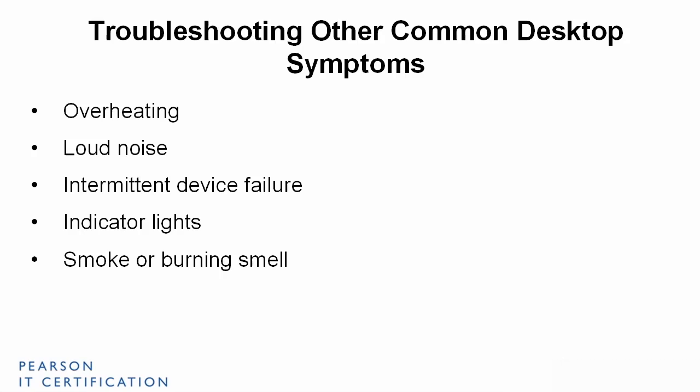Some power supplies have a burn-in period of about 24 to 48 hours where there is a slight odor. That's a little bit different, and that may be normal. Now, if you have a system you're working on, you'll probably just want to run that in the lab until that odor goes away. Make sure that it is a burn-in. But if something goes wrong, it's usually going to be much more potent than that burn-in period smell. So keep that in mind.